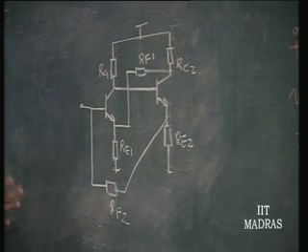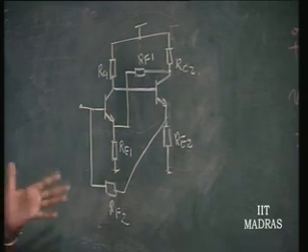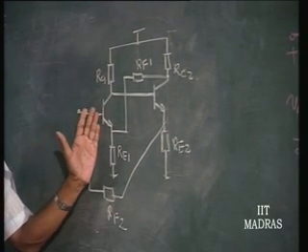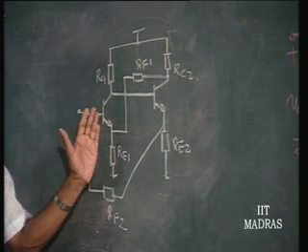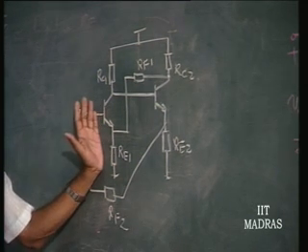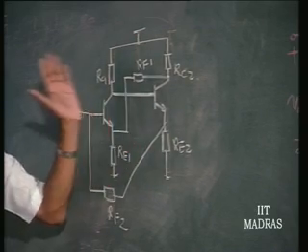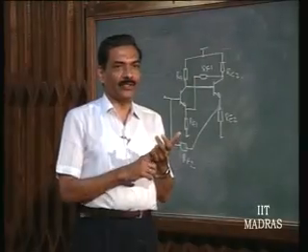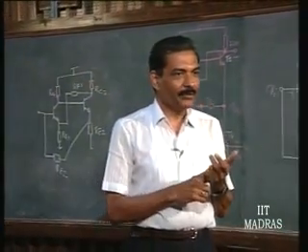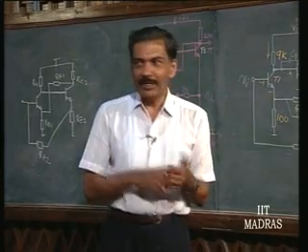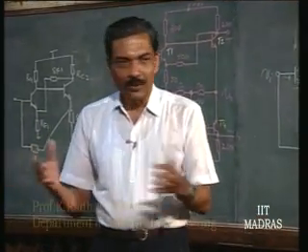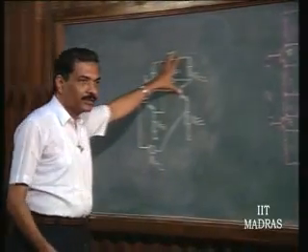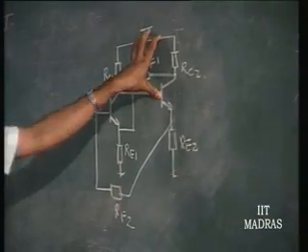So, please analyze this circuit using SPICE, right. Please analyze the circuit first with alpha being assumed to be very close to 1. Please analyze this circuit and find out the input impedance and output impedance and voltage gain and current gain for this. Both voltage gain and current gain are going to be stabilized. Apart from that, input impedance and output impedance will be stabilized, which can be made 600 ohms or 50 ohms or whatever it is, depending upon the drive that you require. Okay? So, please analyze the structure using SPICE as well as your analytical tools. Okay. Thank you very much.